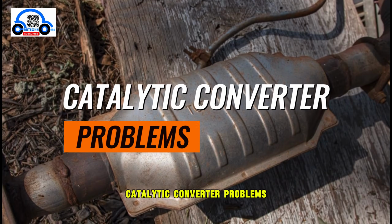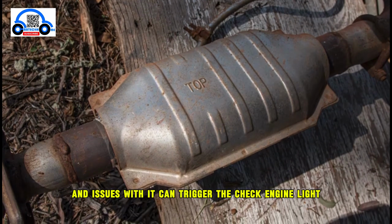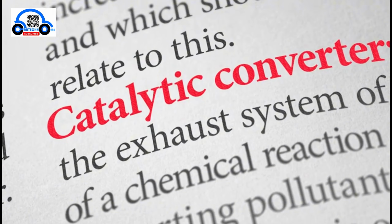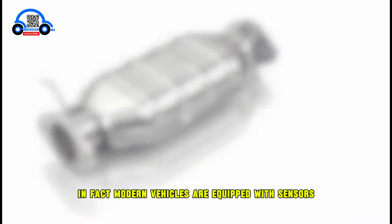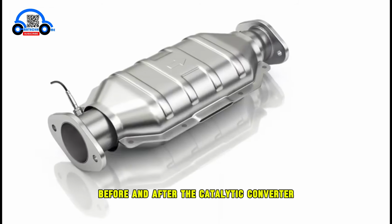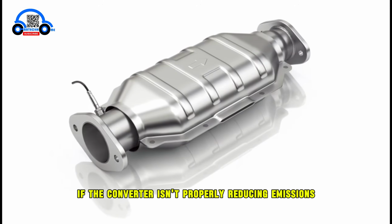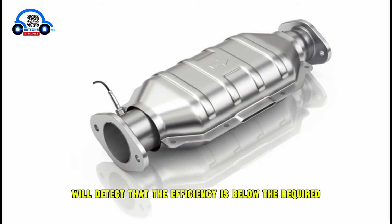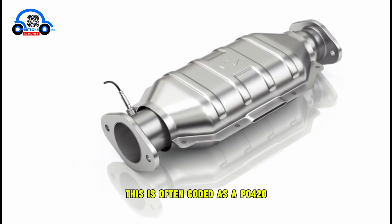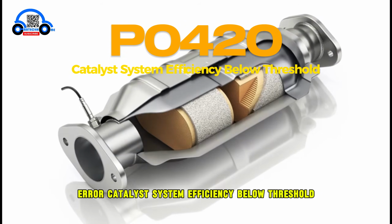Catalytic converter problems. This component helps reduce exhaust emissions, and issues with it can trigger the check engine light. Modern vehicles are equipped with sensors before and after the catalytic converter to monitor its efficiency. If the converter isn't properly reducing emissions, these sensors will detect that the efficiency is below the required threshold. This is often coded as a P0420 error, catalyst system efficiency below threshold.